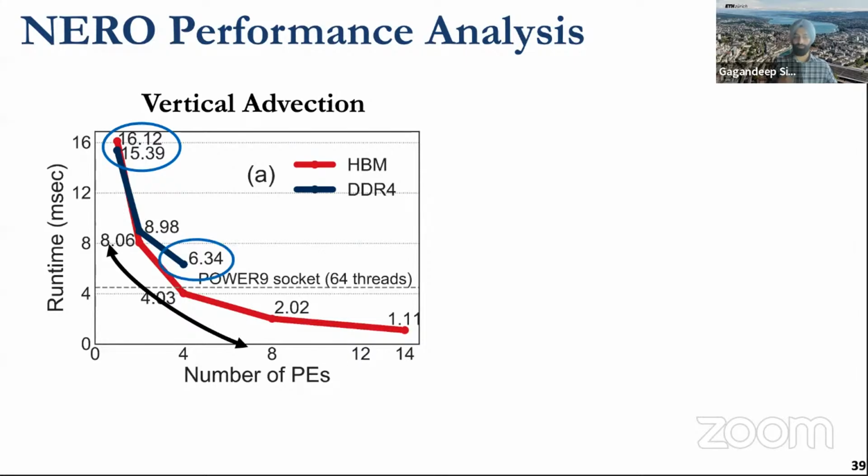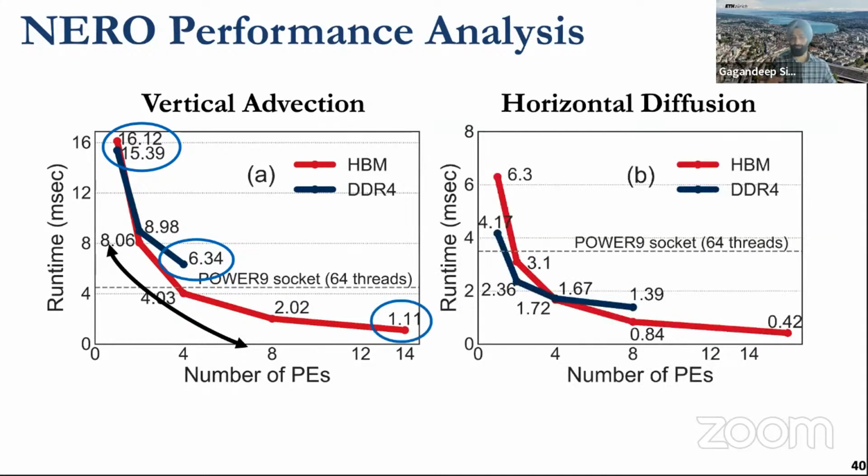With, for example, four processing elements, the DDR memory can't provide the large number of channels which HBM can provide. So we start seeing congestion, because different processing elements are fighting to use the same channel. In that aspect, HBM provides really great scaling capabilities which are not possible using previously available memories.